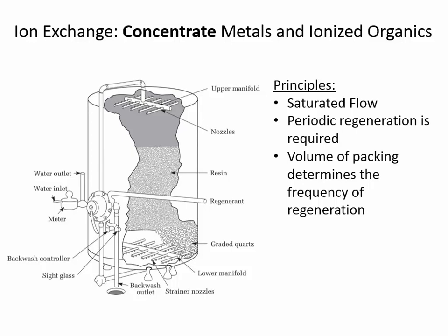And so when you're doing what's called backwash, you're redirecting the regenerant through the beads, you have to recollect the extra water. So you're going to send the water the other direction, this regenerant that makes the resin work again, and now the waste is concentrated, so that originally when we were treating the water that went through here, the concentrations of the metal were probably low. But it accumulated inside of the tank, and then during the backwash process, we'll have less volume than originally went through there. So there's still some waste that has to be disposed of, but it's a way that we can concentrate a liquid waste.